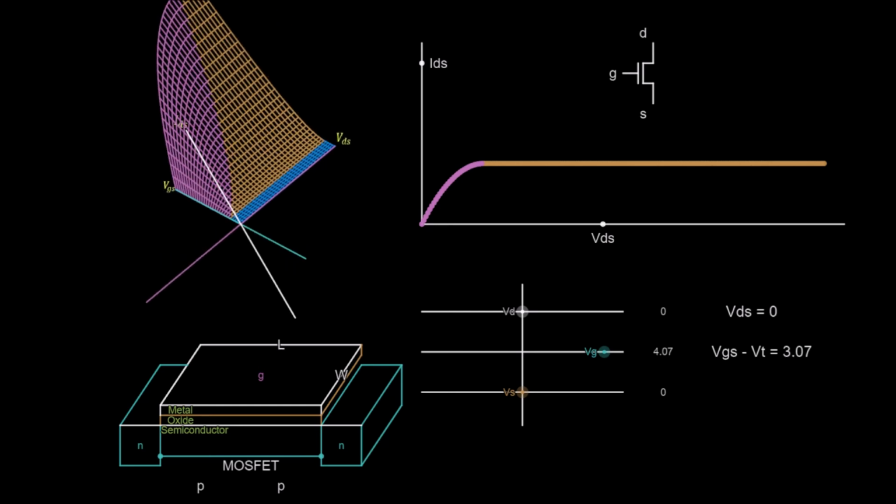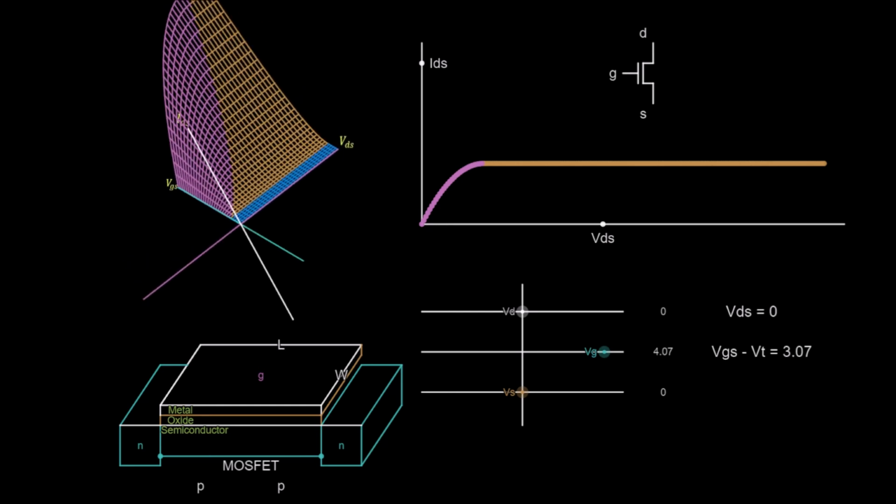So if we head to that different angle, you see we're going to have our VGS here. So that's our gate to source voltage, and this is our gate to source voltage here. And it's going to be working our way along the back of this graph here, and we're going to be picking out individual transfer characteristics dependent on that value for VGS.